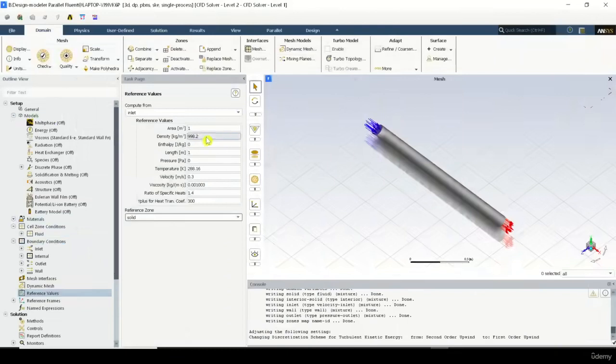So this verification is important. This will represent whether the material is changed or not. Clear? So if you have done something which has not been saved in the background, then you will be having the density as 1.225 only even after selecting the inlet. This indicates the material is air for the simulation. So you have to go back to the cell zones and assign it as water, right?